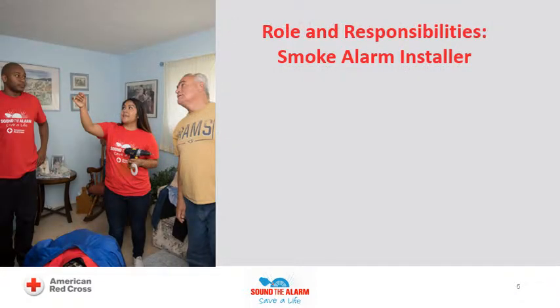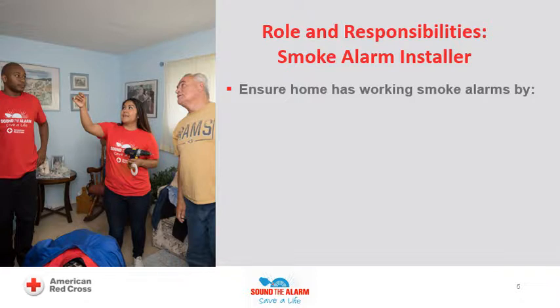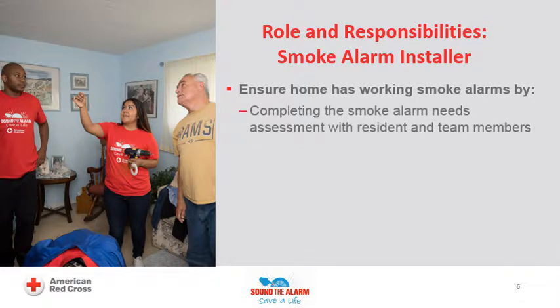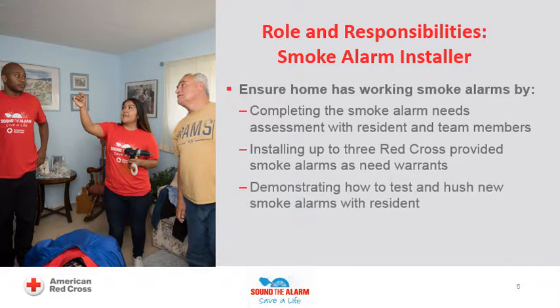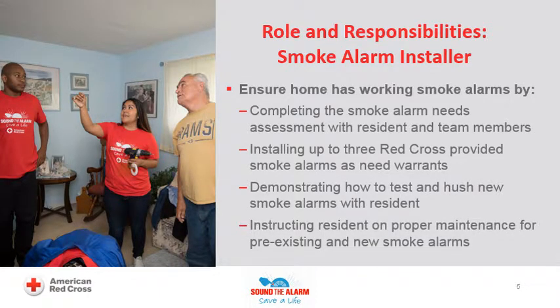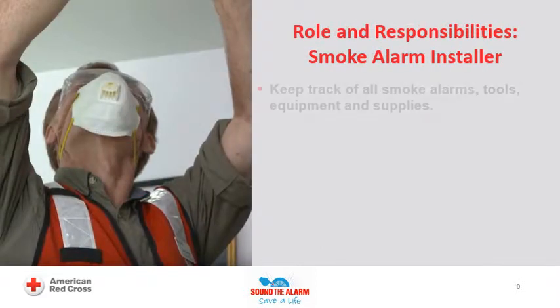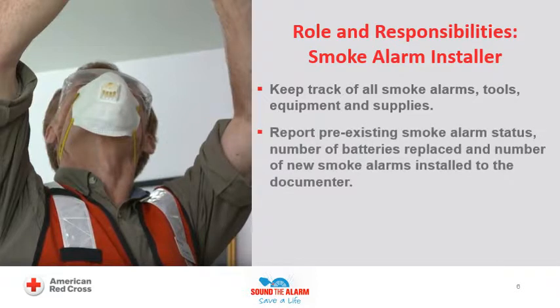The main responsibilities of the smoke alarm installer during the in-home visit include the following: ensure that each home has working smoke alarms to provide adequate notification in the event of a home fire. Complete the smoke alarm needs assessment with residents and team members. You may install up to 3 Red Cross provided smoke alarms as need warrants. Demonstrate how to test and hush new smoke alarms with residents. Instruct residents on proper maintenance for pre-existing and new smoke alarms. Keep track of all smoke alarms, tools, equipment, and supplies. Report pre-existing smoke alarm status, number of batteries replaced, and number of new smoke alarms installed to the documenter.